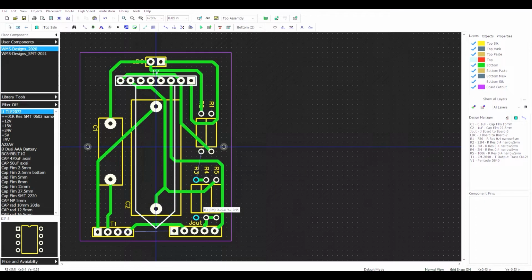You'd want to make sure you watch out for things like if I had AC in this. This is DC going to the heater, but if I had AC going to the heater, I'd want to make sure those wires were kept really, really far away from all the audio. In this case, it's DC, so it's not a big deal.